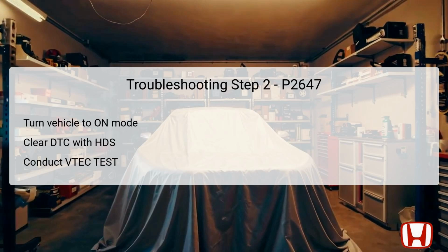In the second step of the troubleshooting process, begin by turning the vehicle to the on mode without starting the engine. Utilize the Honda Diagnostic System, HDS, to clear the stored DTC. This step is essential as it resets the system and allows for fresh data to be collected.